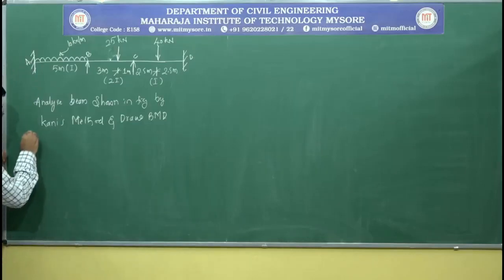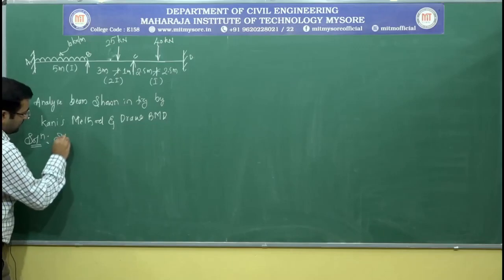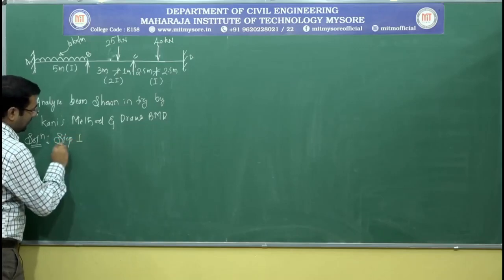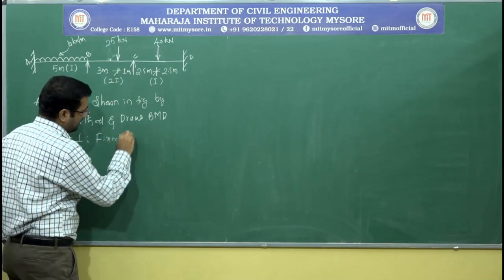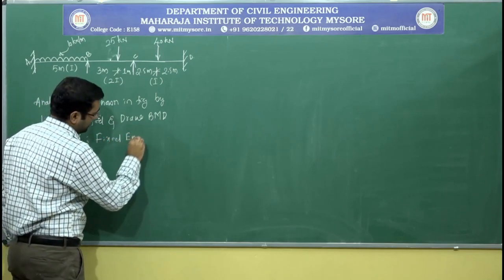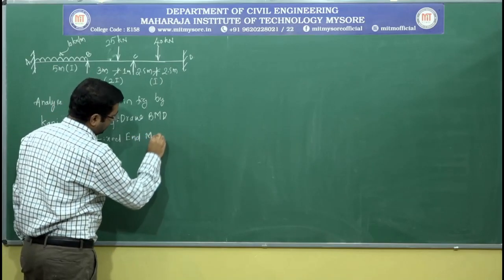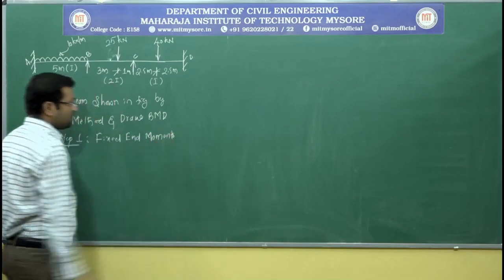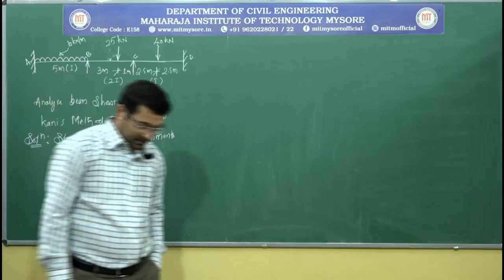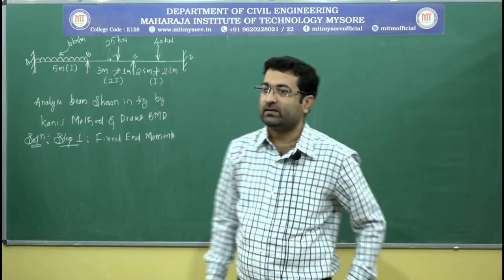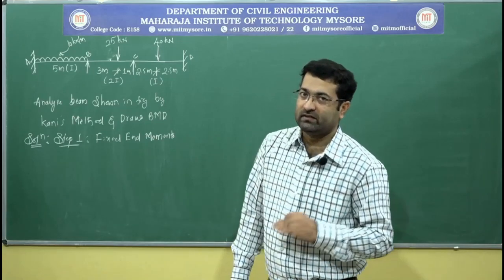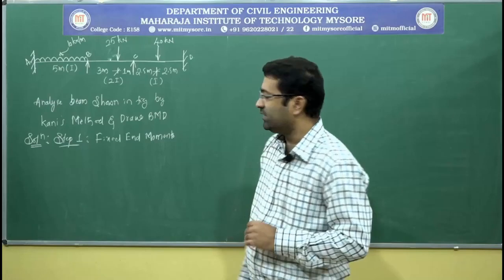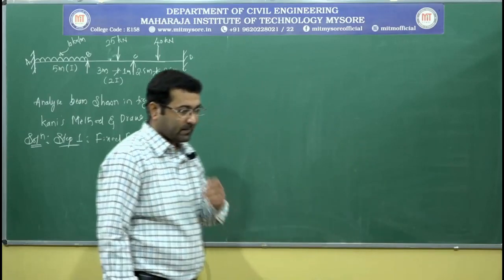So let me start with that solution. So the step number 1, it is the fixed end moments. From the last two modules we have been discussing how to calculate the fixed end moments. So here also we will have the same kind of formulas to work out the fixed end moments.